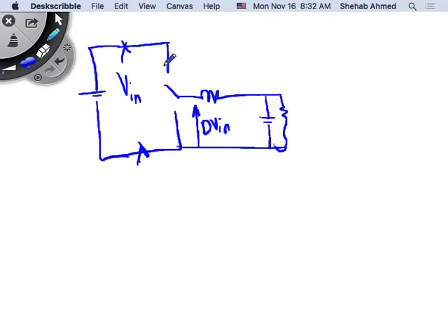Also, we said that all our circuits will behave in the same way, and I will look at where the switch is, and it will happen to be, for the buck converter, again, I can go to my table. This is my polarity of voltage, my current polarity is this way, I can put my switch and diode. I put my switch and diode, I know it's up here, right? I know my switch is up here for the buck converter. So, current is coming this way, and current is coming this way, and the sum of these currents is equal to this IP current or IL current, right? This current will always be dependent on duty ratio.